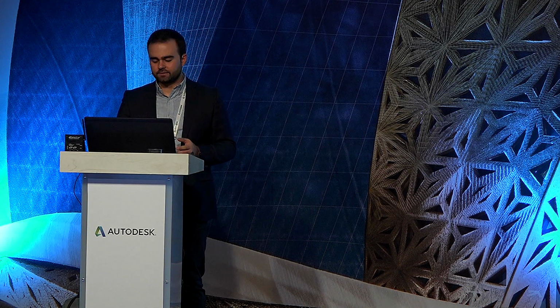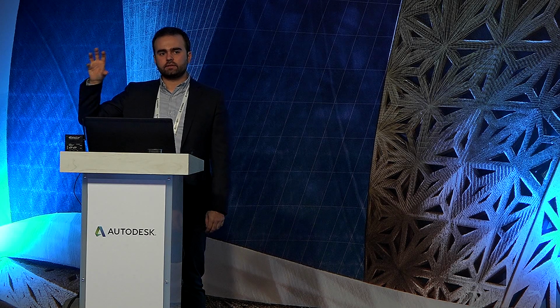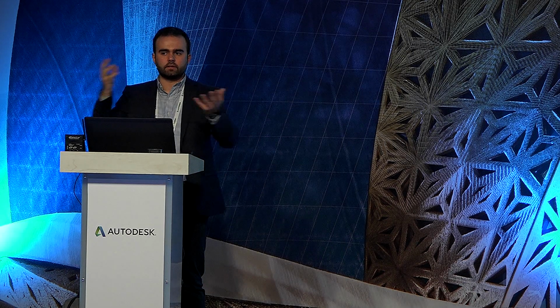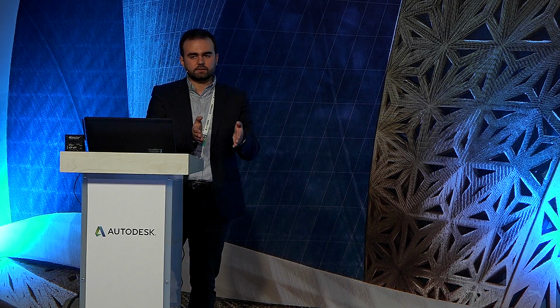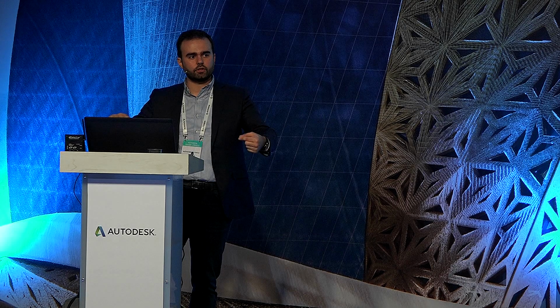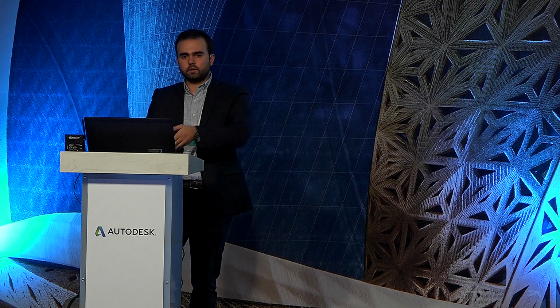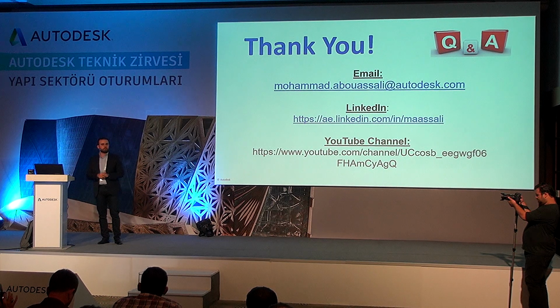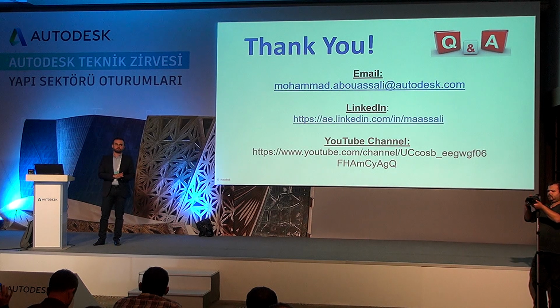So what I want you to take from this session is that the way of capturing data is changing. Now people are using point clouds, laser scans to get a lot of data and analyze it. The way of analyzing this data is changing with InfraWorks, automation, artificial intelligence, detecting the surface, the 3D objects, and the alignments. We move all that data to Civil, where we basically create the surface and the new corridor for the road that we would like to maintain or rehabilitate. And then we can move back into InfraWorks if we need to do any traffic simulation to check if the construction process will not affect the existing traffic and cause a lot of delays. That's basically the workflow that we have in hand.